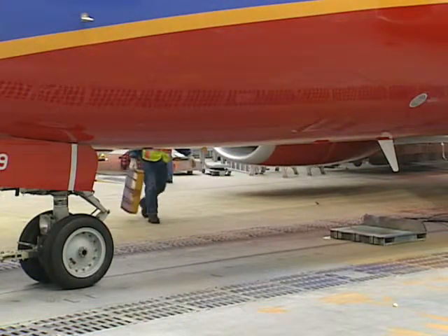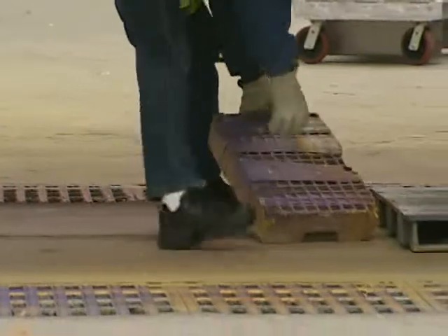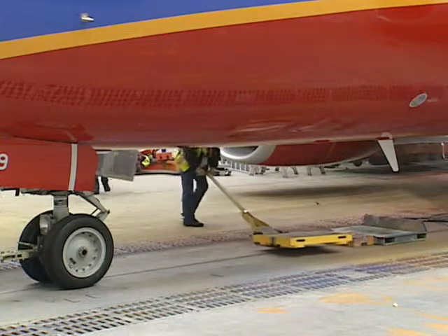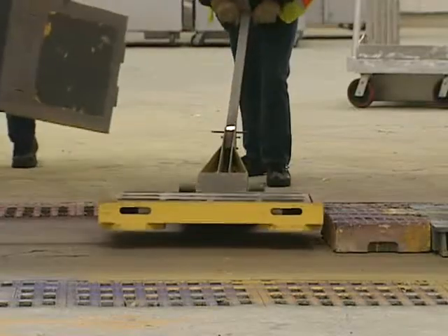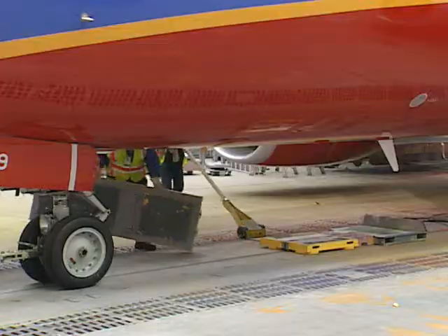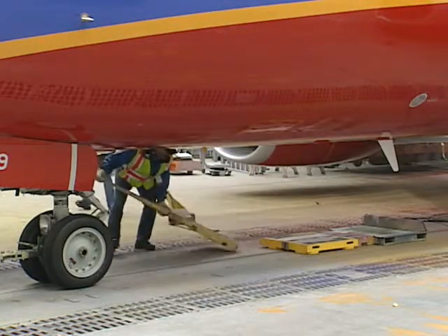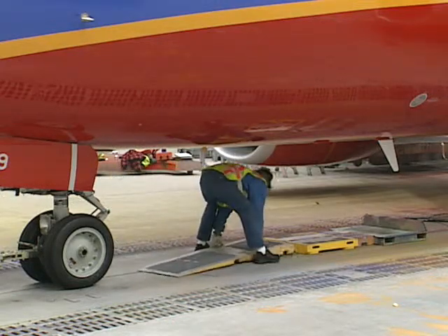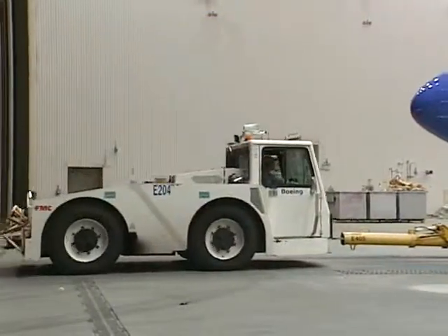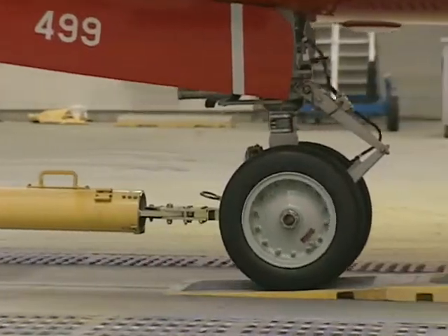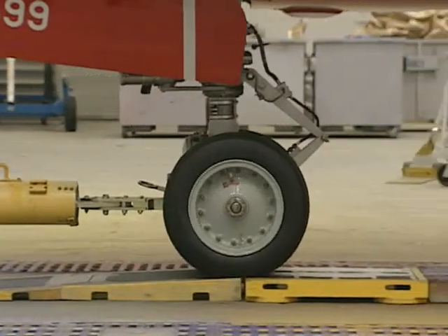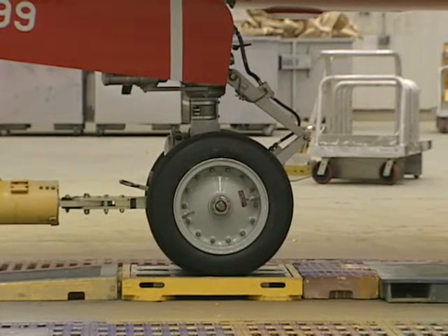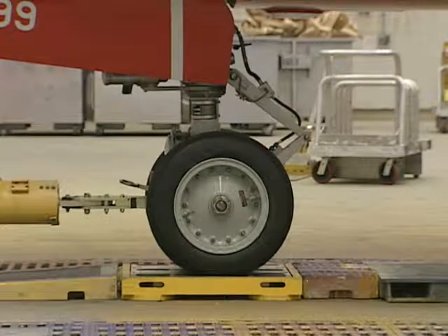Set up the ramps, scales, and spacers according to the manufacturer's instructions. On the 737, you will need one set for the nose gear and one for each of the main gear wheels. Before taking any readings, you should exercise the scales by temporarily towing the airplane onto the scales. This is to make sure the platforms are operating freely and giving accurate readings.